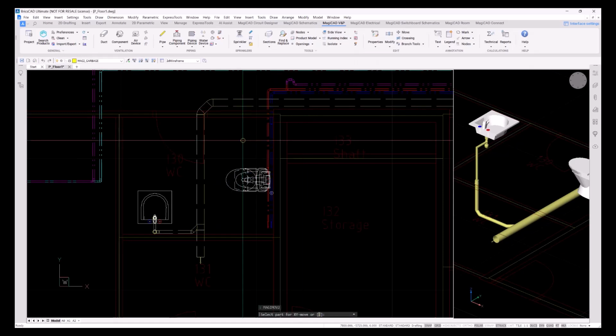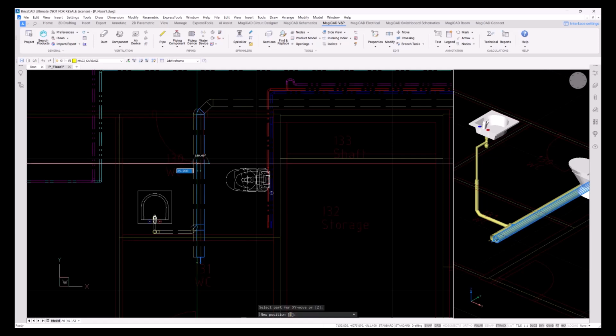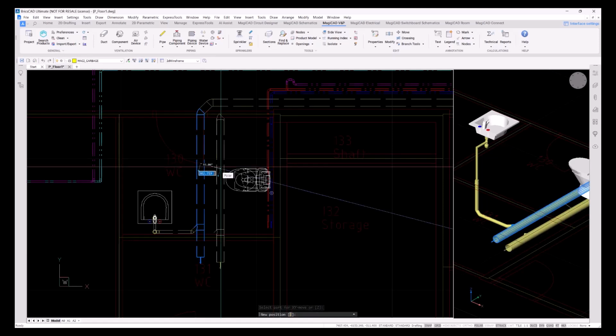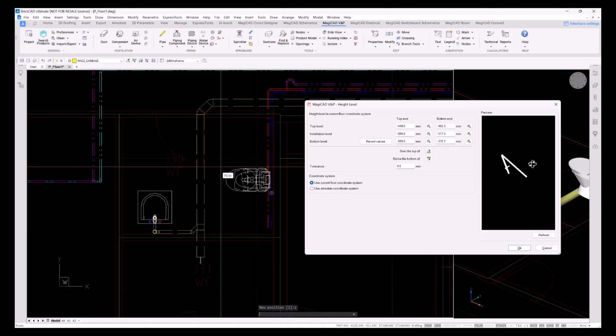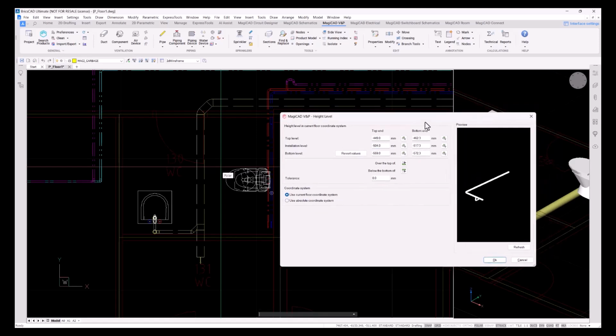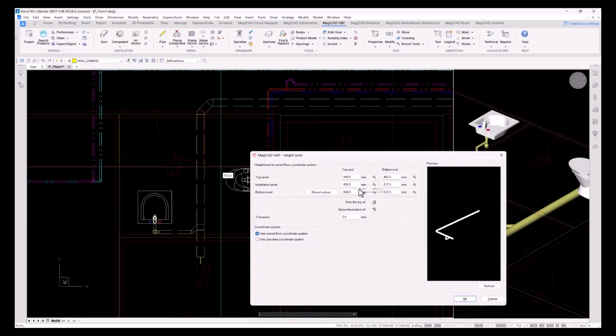Also here we can make small changes, if we needed to change elevations afterwards, after we have made connections. We can take the set and here see how it looks in the 3D preview, and maybe make small adjustments here if possible.